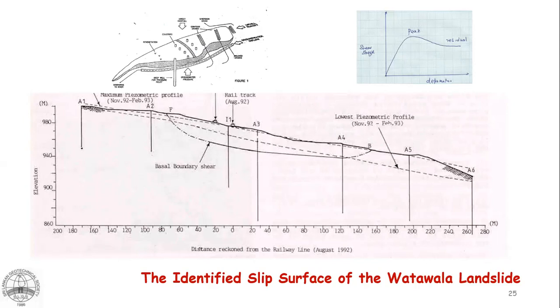So therefore, in this case, they proposed directional drains. A drain initiated from here, going just below the critical identified failure surface and daylighting somewhere there. So there were 13 such drains done to cover the planned area, and perforated high density polyethylene HDPE pipes were installed in those drains.